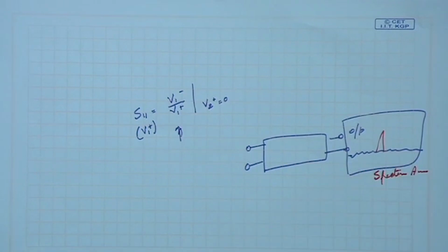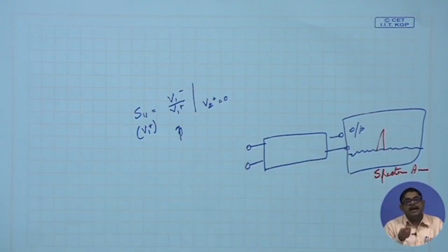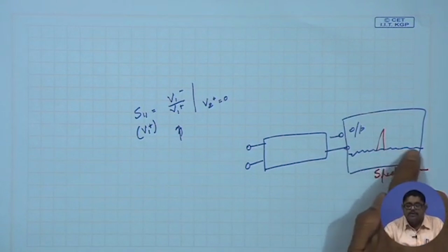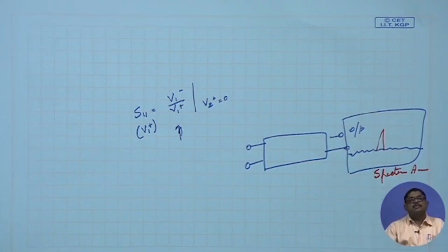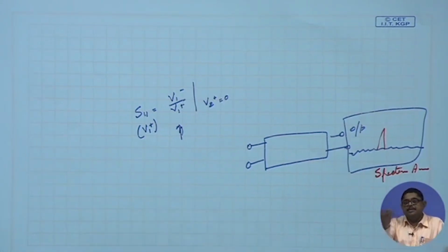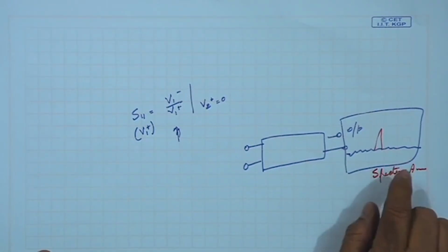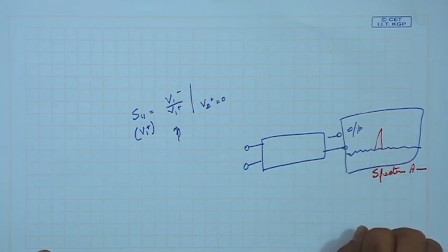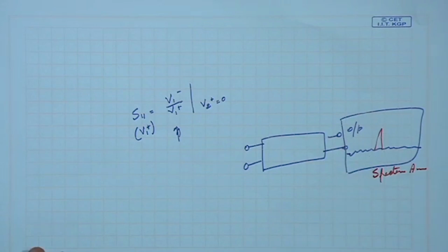What is this? There is actually always noise present, particularly this block, which is adding some noise. That is the noise floor of the device. In oscilloscopes, in multimeters, in spectrum analyzers, everywhere you have noise. In a multimeter you do not have a visual display of that, but in an oscilloscope or spectrum analyzer you will see that there is noise.